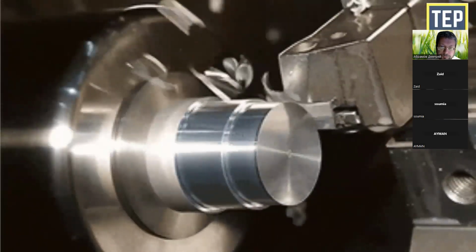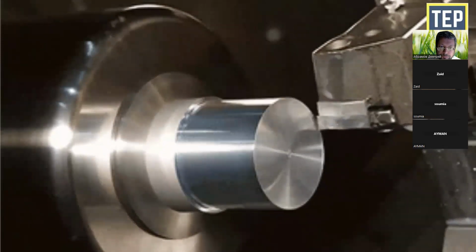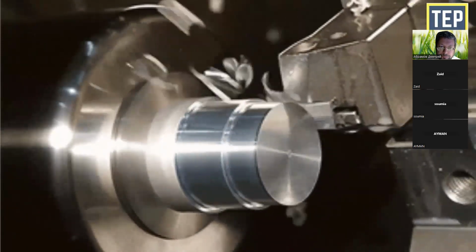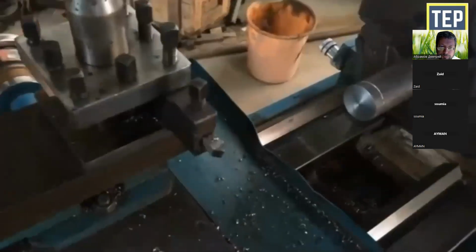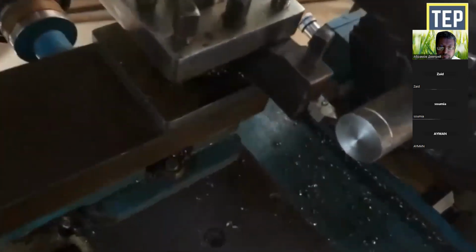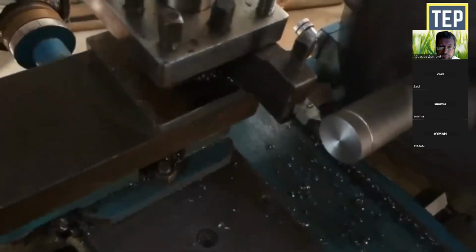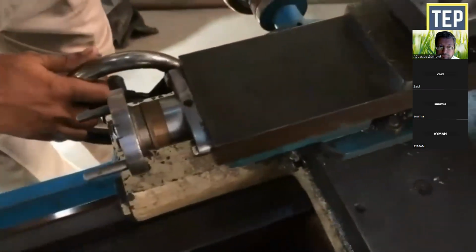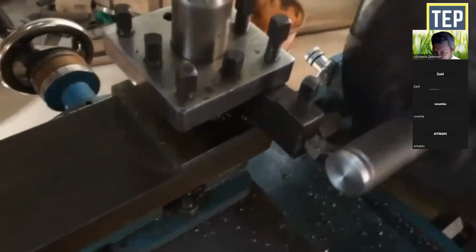Turning is the most common type of operation of removing the excess material from the workpiece to produce a cylindrical surface to the desired length. The job is held between the centers, or a chuck, and rotates at a required speed. The tool moves in a longitudinal direction to give the feed towards the headstock with proper depth of cut. The surface finish produced by this operation is very good.